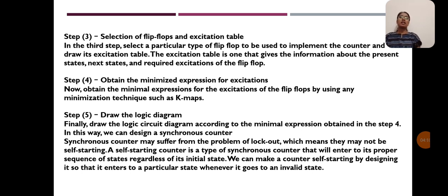Step 4 is to obtain the minimized expression for excitations. Obtain the minimal expression for the excitations of the flip-flops by using any minimization technique such as K-maps. Fifth is to draw the logic diagram. Finally, draw the logic circuit diagram according to the minimal expressions obtained in step 4. In this way, we can design a synchronous counter.